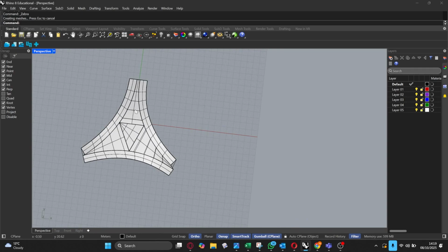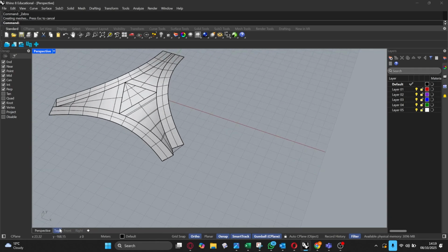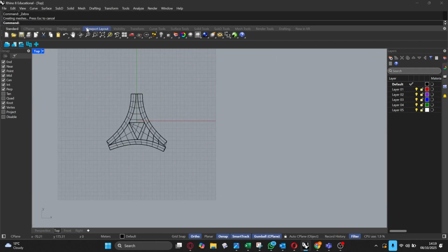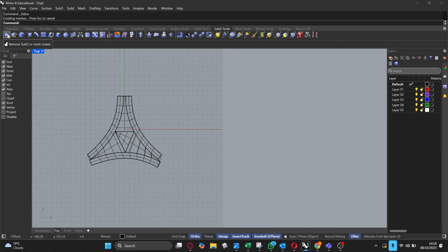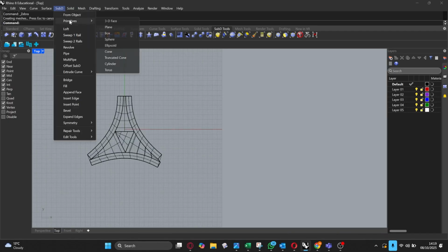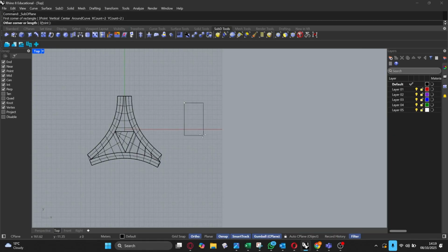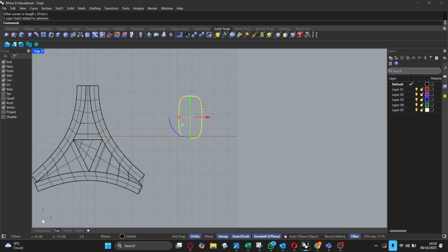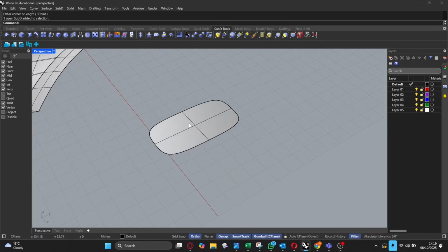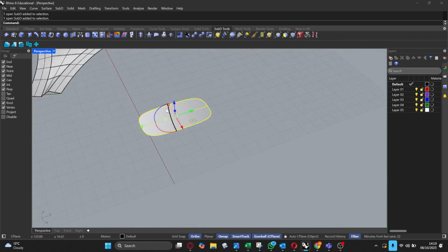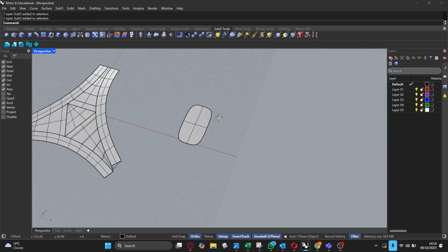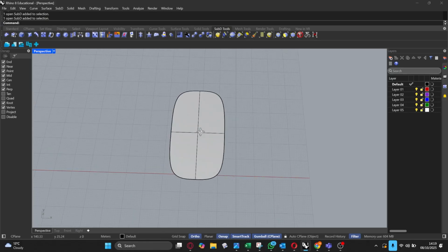So to resolve that challenge, what we would need to do is we could start to play with some of our different SubD tools, and we can start to create a SubD surface, and then we can make the same kind of geometry from this SubD. So I'm just going to go here and I'm going to click on primitive, and I'm just going to put a plane on here. And the way that SubD works is we're working with faces, we're working with edges, and we're working also with points or vertices.